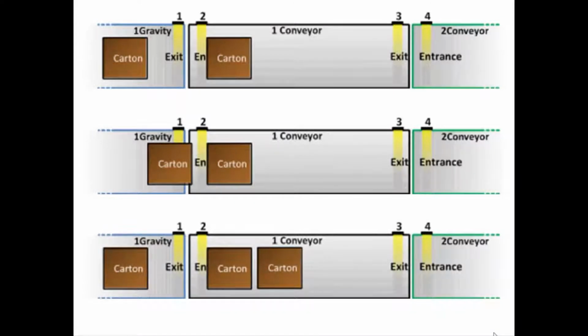And the logic then says, well, there's only one carton on one conveyor, it'll hold 4. It starts up one conveyor and it pulls that carton that was resting against its leading edge through photo I2. In other words, it turns on until the carton breaks photo I2 and then continues to run to the trailing edge of that second carton. Then it stops.